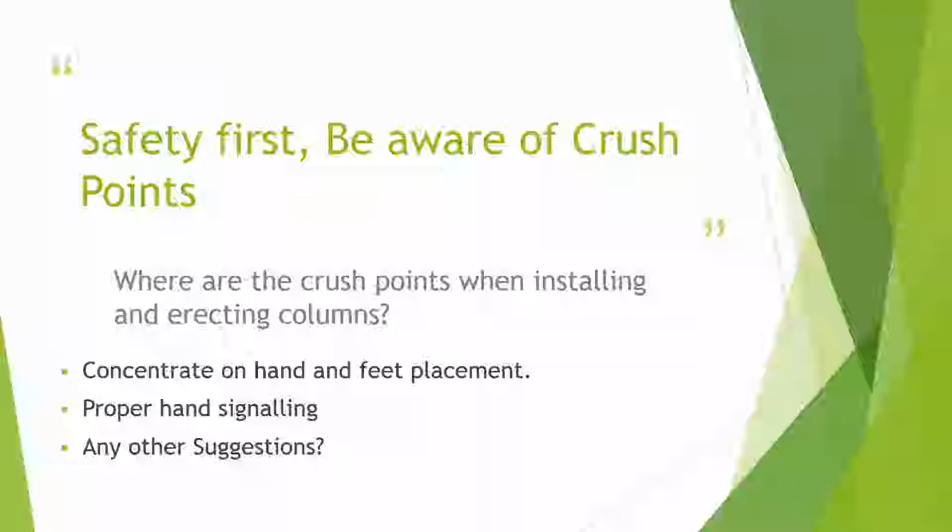Because should we really put all our trust in machinery and hydraulics? No, they fail, unfortunately. So we've got to be well aware of that and not trust them. You always keep your body away from the load and guide the steel column by using tag lines. We use those tag lines so that our hands don't always have to be on the steel itself.